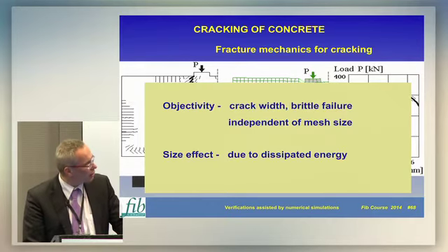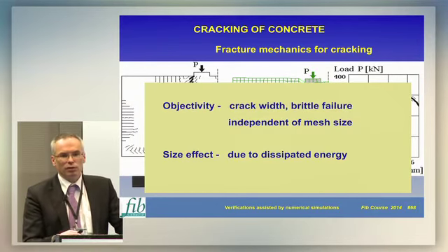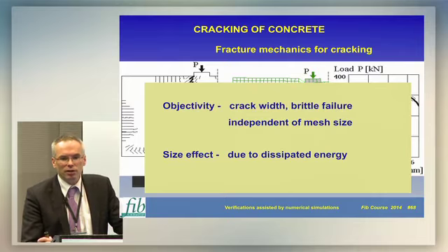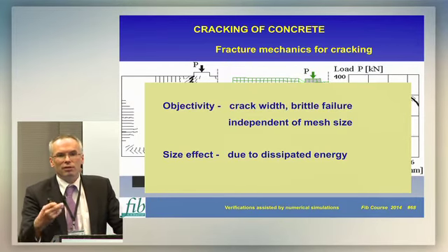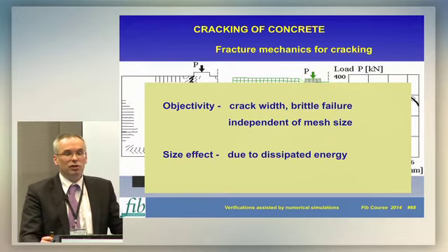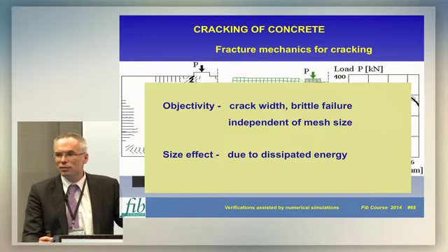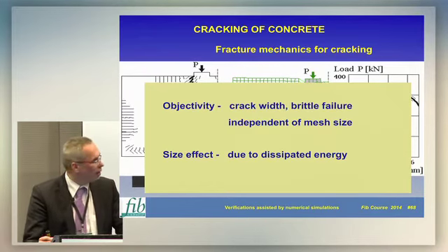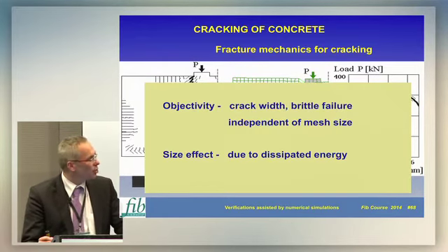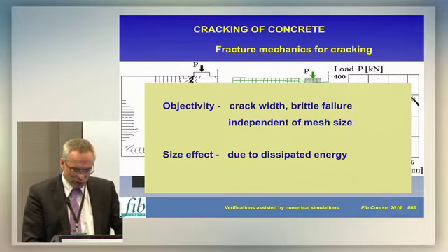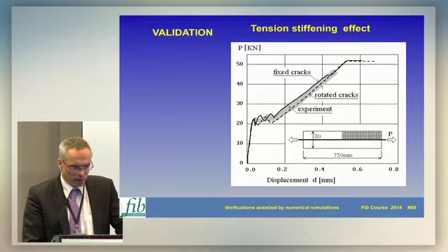The good thing is that it can then also capture the size effect. So nonlinear analysis will automatically take into account the size effect of your structure, at least the energetic size effect. Sometimes there is also a statistical size effect, which of course cannot be addressed by this model, but the energetic size effect can be very well captured.